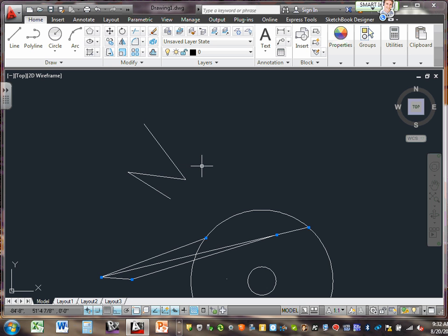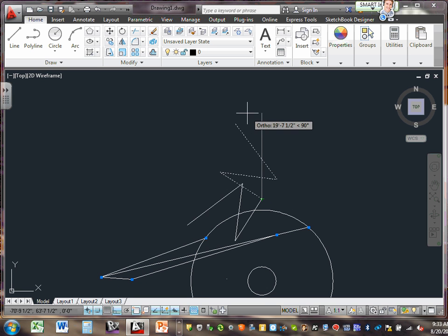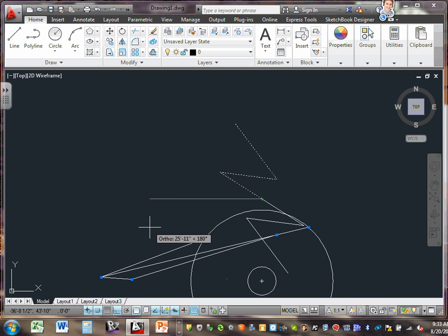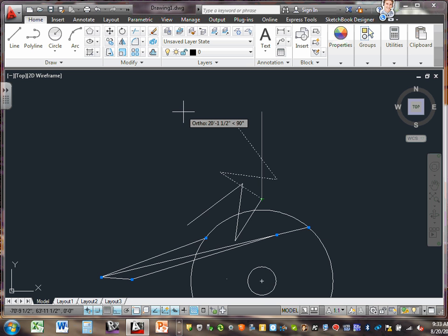Most of the stuff, Karen, that we do is we rotate at 90 degrees. So what we do is just highlight it. Right click, pick the end of it. Oh, I moved. This is move. So rotate, pick it up, right click. Oops. Right click, pick the point that you want to rotate, and then put your ortho on. Oh, it was on. And you start, can you guys see, start moving in 90 degrees? That's what most of the stuff that we do. We move in 90 degrees. If you want other degrees, you can move it.